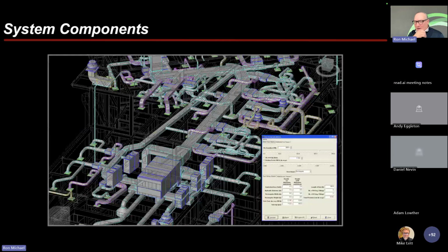Now, real quick, I'm going to go through this again, kind of real quick, because I know we're coming down on time. I want to get to some of my examples of bad selection. So, for those of you working in Revit, you've got your sheet metal package. I just want to point something out: when you look at a component and the pressure loss out of SMACNA, it's again also based on laminar flow in, laminar flow out.